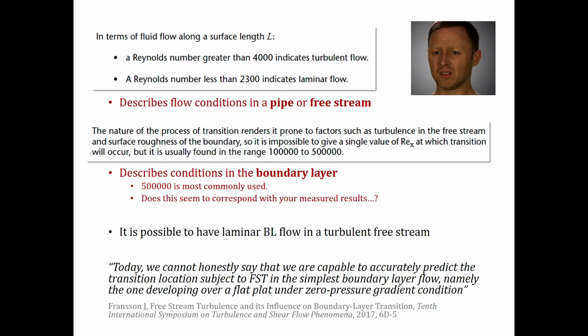So it sounds a bit vague. It is. It's not easy to do. It depends on all kinds of things like surface roughness, the effect of turbulence in the free stream, and so on. The angle, if you're not perfectly at 0 degrees on your flat plate, is going to have an effect as well. All kinds of things lead to variations in that value.